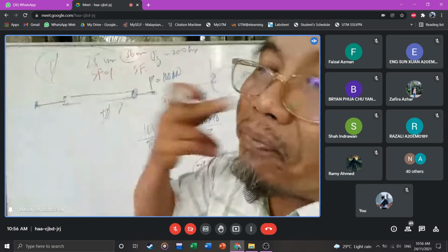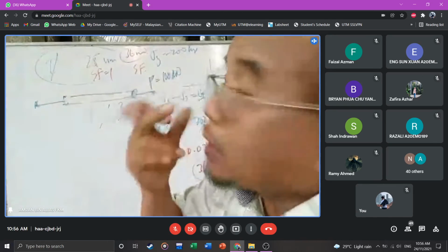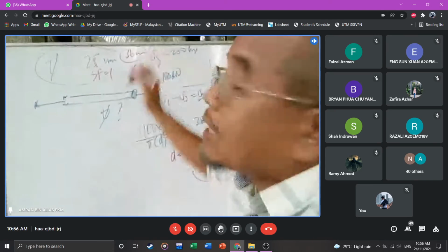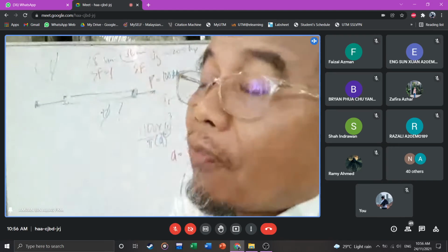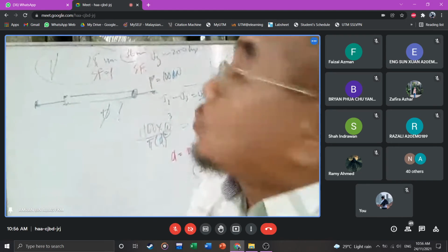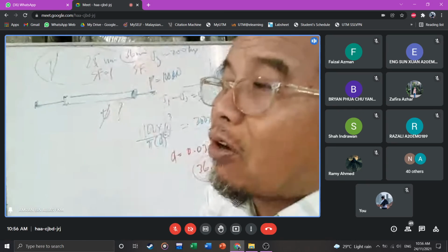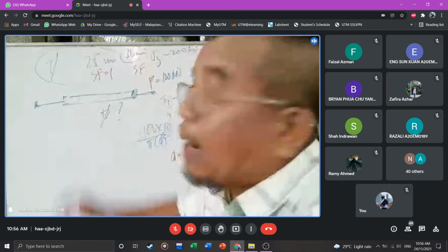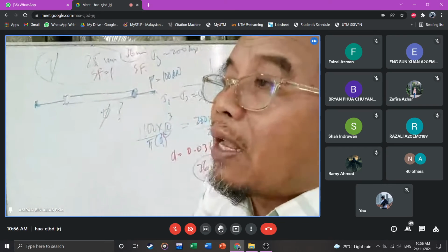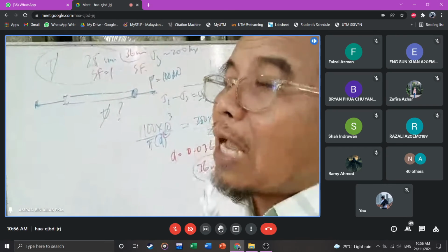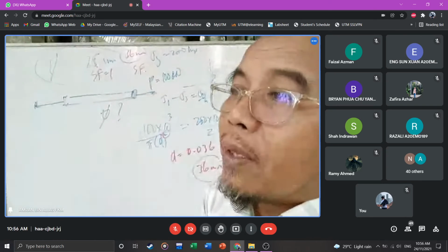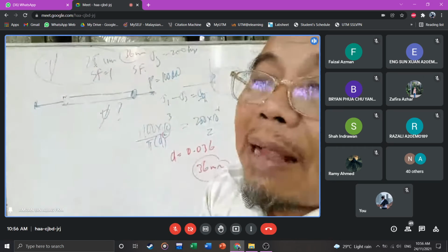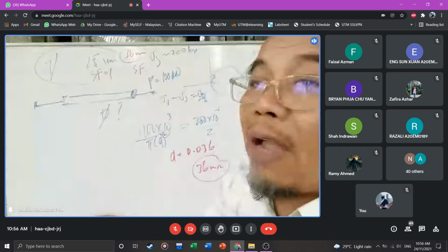This is dangerous here. So this is normal engineering material, and the loading is always important. So you decide higher than 36, because you want the safety factor higher than 2. If you buy it, there is 36 or 37 or 38 mm. Sometimes they don't sell 37, only 36 and 38. Sometimes only 35 and 40. The hardware store doesn't sell that size, 37. So 35 or 40, you buy 40.